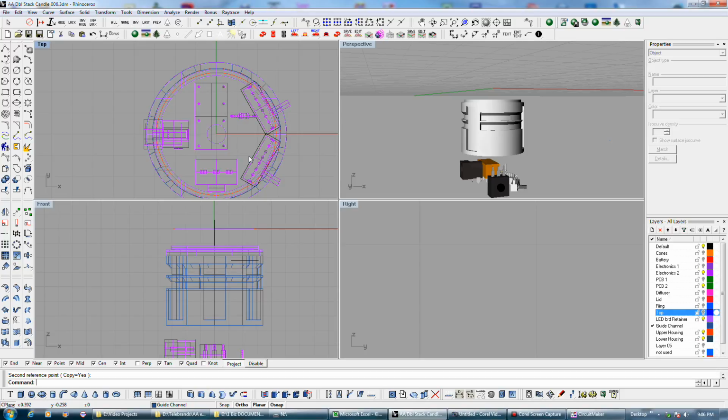And even then, I still may not have enough room for all the resistors and everything, plus the traces and everything else we need to do. It becomes a bit of a wild card. But it is possible for me to make a little well below the circuit board, 1/4 of an inch or so clearance, and just attach some lead wires to it, because I only need a lead wire on this pin and this pin, because these are the coil pins, and then this one and this one, I believe, because that's normally closed, I think.